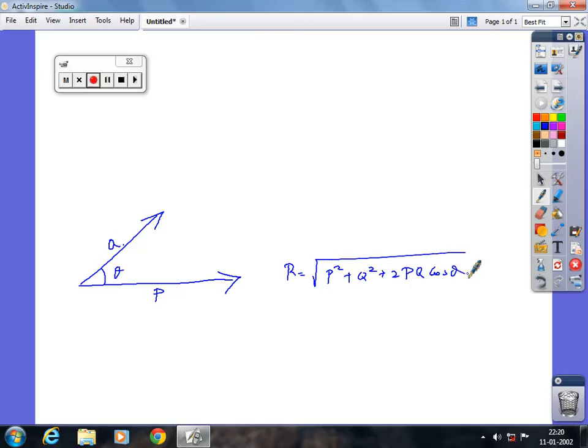The third heading, you can write it as analytical method. And you keep a full stop. And then below that, you write: the resultant of two concurrent forces can also be obtained from the formula capital R is equal to root of P square plus Q square, a full root. And what is marked on the board, you can just make a note.